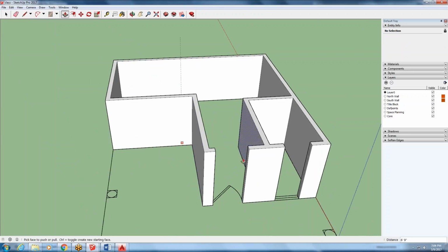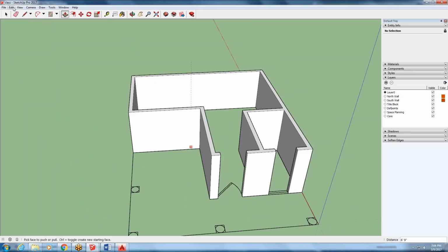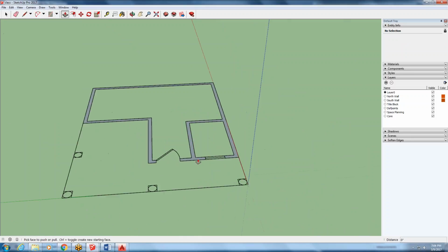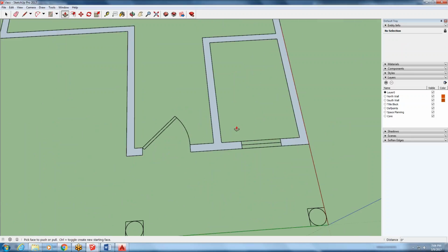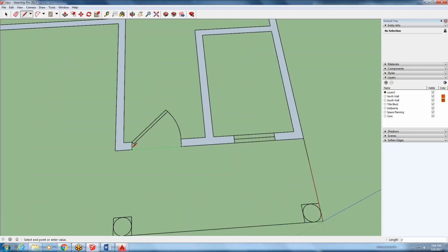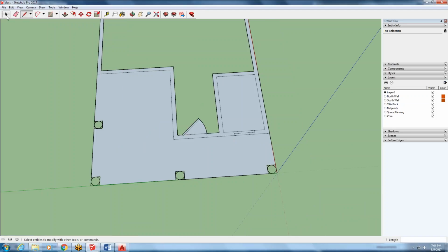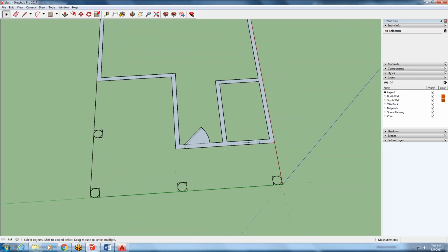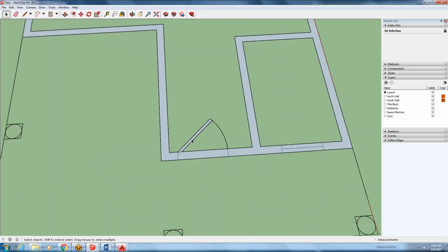I have this in here that I would have wanted to close. So let's undo. Wherever there's a gap, like a hole and window, instead of having a gap like this, it'll actually be easier on your mind if you close it for this week. So close it by drawing all those lines through and closing those loops. Okay, and then you can go out and delete extra information that got added in by closing them.